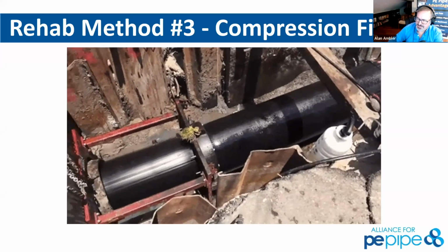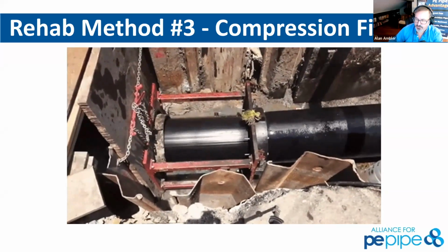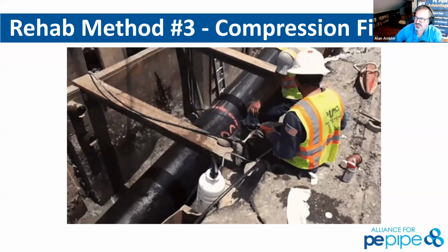Semi-structural liner would be not a full structure, not withstanding the full pressure class, and then working with the existing host pipe.